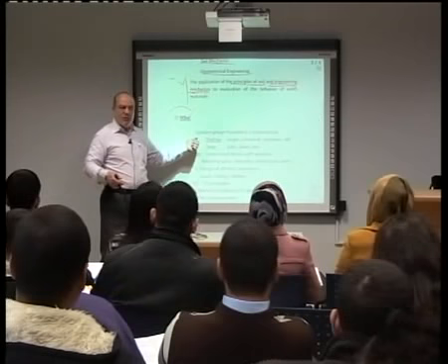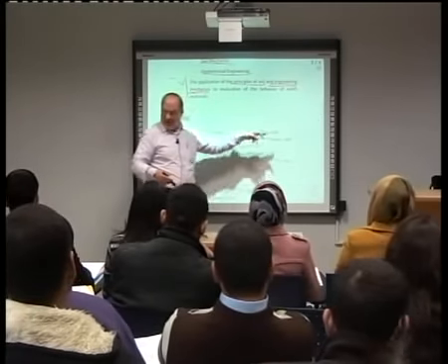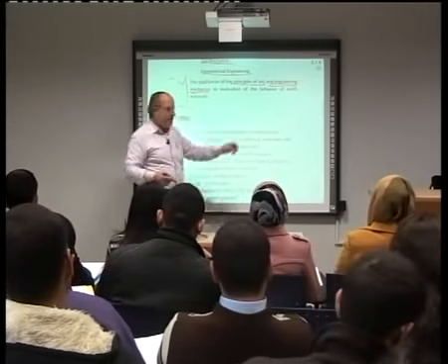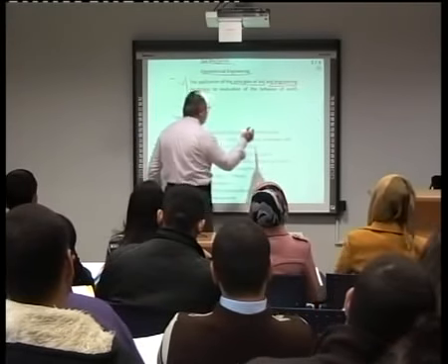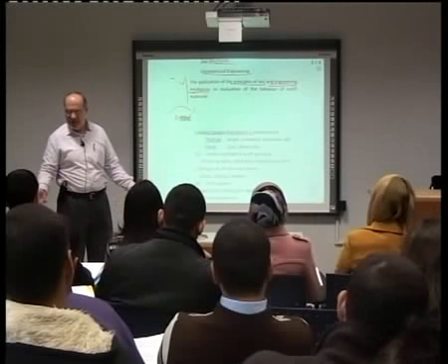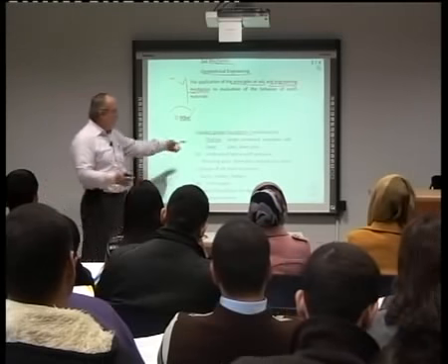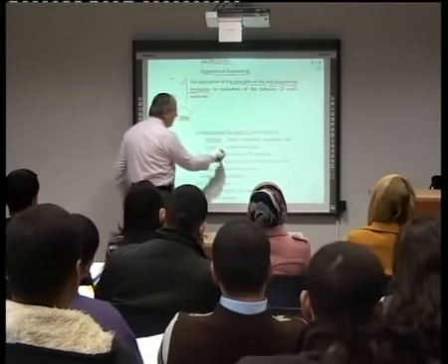Okay? Why do we study soil mechanics? First, select proper foundation, substructure. You see? So, number one, select proper foundation. What kind of foundation do I have to use for constructing this building? Do we have several foundations? Yes, of course. We have shallow foundations. We have deep foundations.